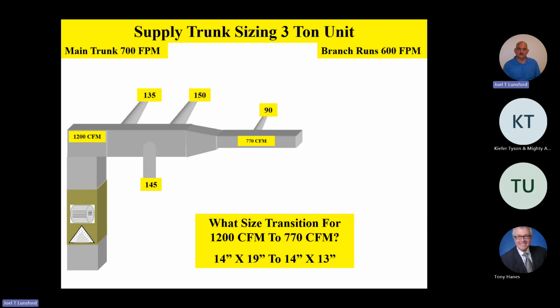Well, nobody makes a 5.5 inch duct, a round takeoff or whatever. And if you're using flex, you go to 6 inch on that one with a damper, so you can do final air balance, because if you take a look at your duct calculator, you only need 5.25 inch duct to provide 90 CFM at that velocity. However, nobody makes that size duct, so you go to a 6 inch duct, and you'd put a damper on there so that you can do final air balance.